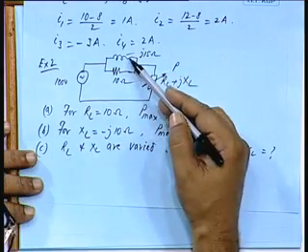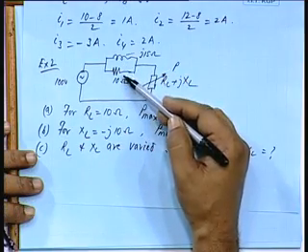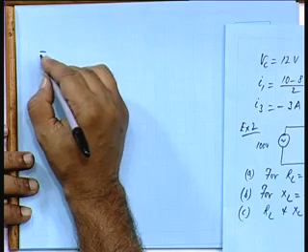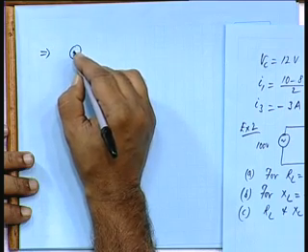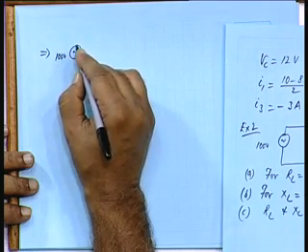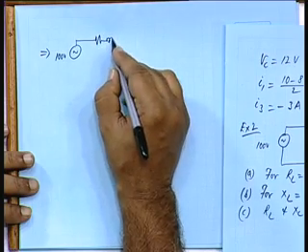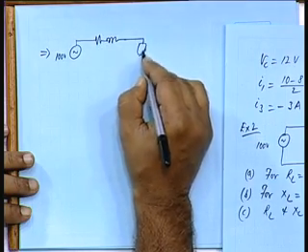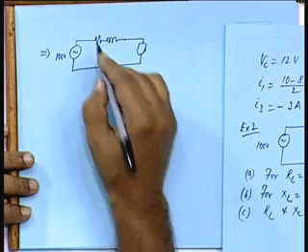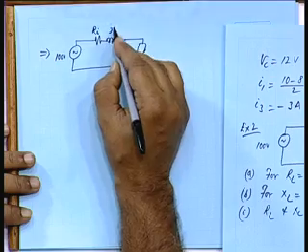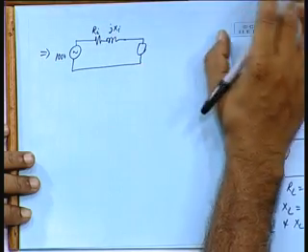Before we attack this problem, we can think of reducing this parallel combination into a single R plus jX form. I can reduce this network to a source with a series impedance, which I will call Ri plus jXi.